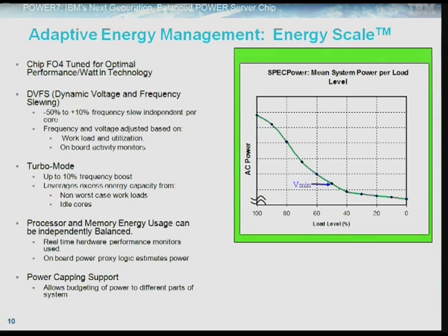Balancing energy between the processor and memory is accomplished by a power proxy. The power proxy calculates the relative power using a set of weighted event counters. The weight assigns energy values for various events like cache misses, floating point ops, memory accesses, etc. The off-chip micro then determines how to optimize performance per watt by shifting allotted power between the processor and memory. Power capping is also supported to enforce a hard ceiling on power if desired.